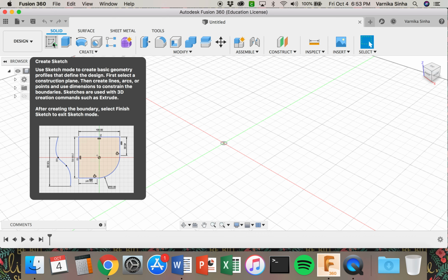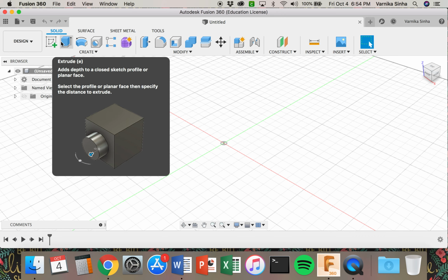As I said before, we're working in a 2D space, making a 3D object. So even before we can start making this in 3D, we have to make it in 2D. So what is creating a sketch? It's making a 2D image of the object that you're trying to make, which becomes useful because you want to think about this orthogonally in the drawings that you made before you start sketching it out, which is why it's useful to make orthogonal drawings. So that's creating a sketch. And creating the sketch is where you also get the dimensions, as you can see in this photo hovering above.